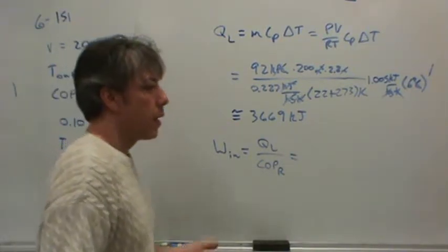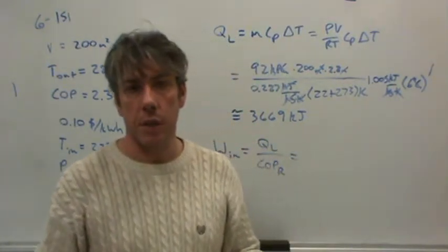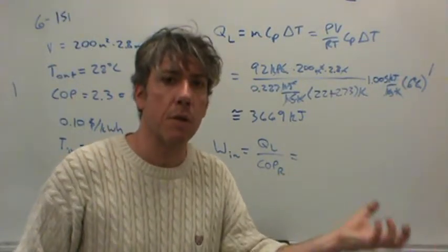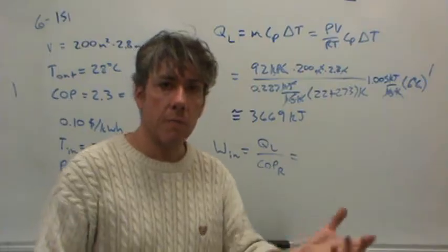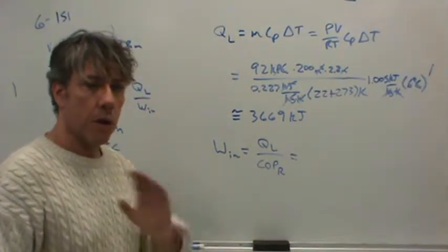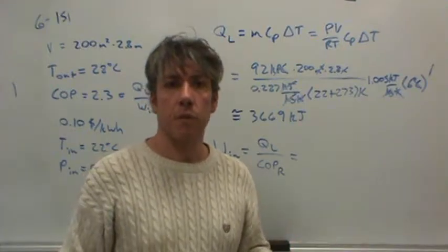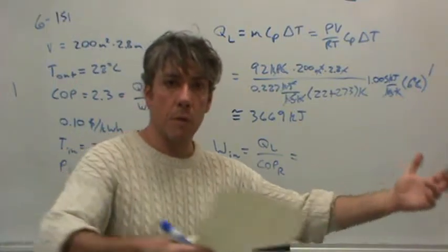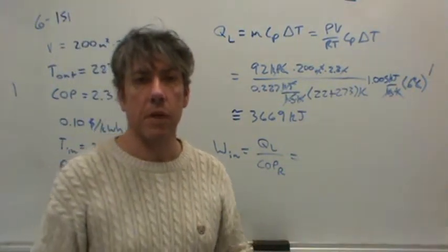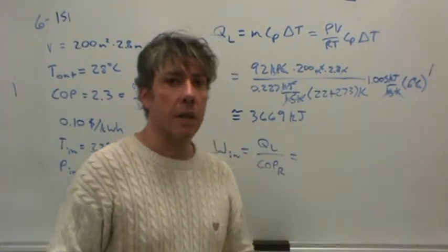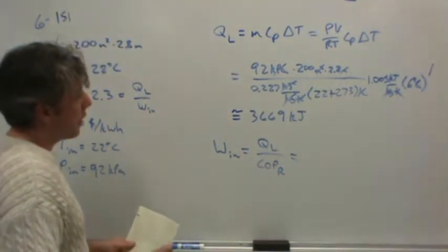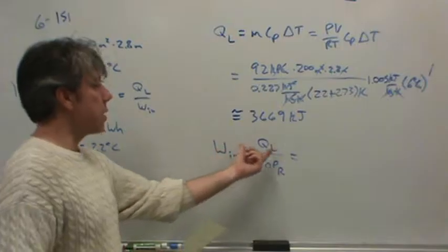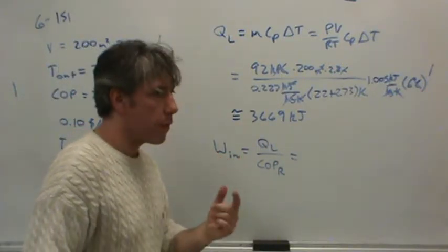This is not really all that strange. We're not talking about destroying energy here. All we're talking about is moving energy, right? So there's energy in the home. It takes less energy to move that energy to outside than the quantity of energy itself. It's kind of like a truck going down the road that's carrying gasoline or diesel or some fuel. The amount of energy required to move that tanker load of fuel from, say, the refinery to the station, is less than the amount of fuel in that tank, at least hopefully, right? But yeah, that's actually the case. So anyway, that's what this is talking about. Basically, we're using electrical energy to move thermal energy. Now, the electrical energy itself also ends up outside.